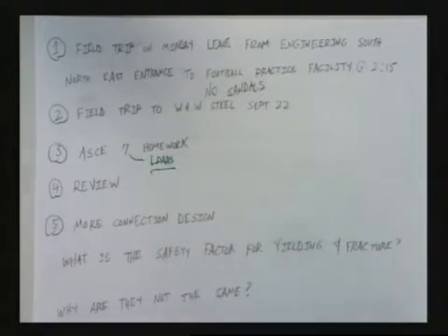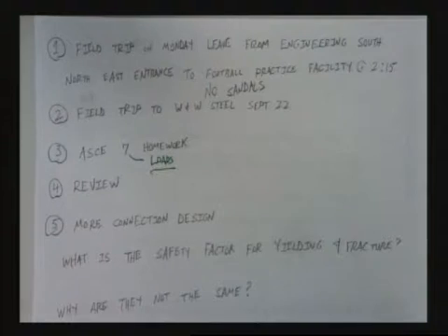Now, when we're designing a structure, do we just do what ASCE 7 says? No. There's things called notional loads or construction loads that ASCE 7 has no clue about, how something's going to be designed, how something's going to be constructed. But it's your job as the engineer to ask that question or to find out how something's going to be designed. You'll oftentimes find that the loads during construction are much, much higher than the loads they'll see in service.